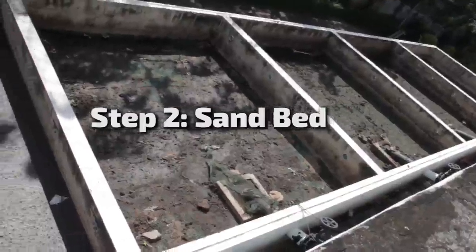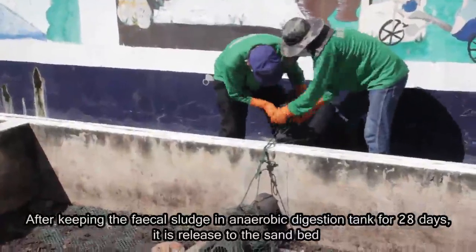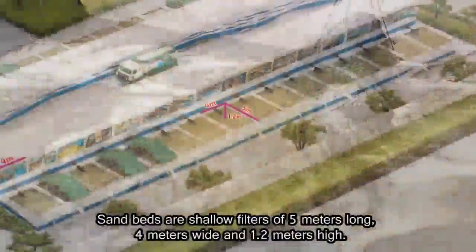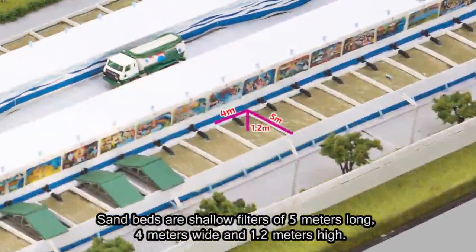Step 2. Sand bed. After keeping the fecal sludge in anaerobic digestion tank for 28 days, it is released to the sand bed. Sand beds are shallow filters of 5 meters long, 4 meters wide, and 1.2 meters high.